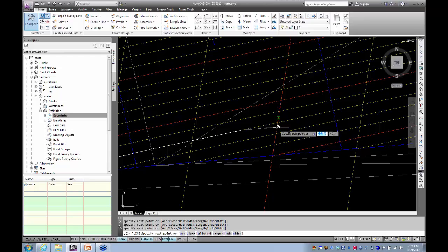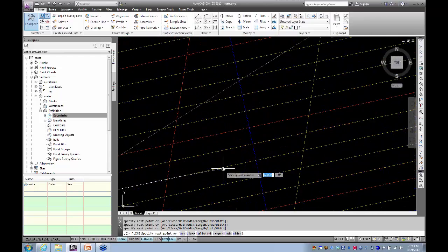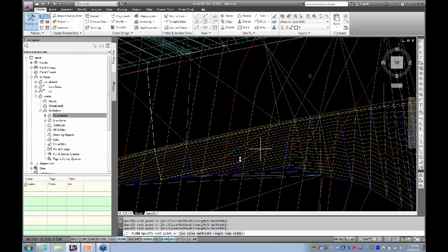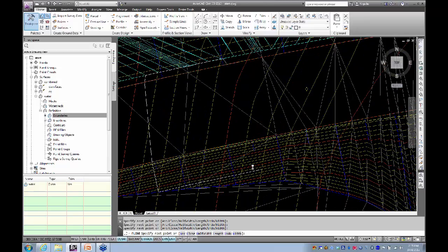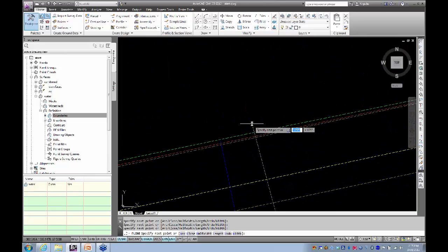So you can make another user-defined contour if you want a specific level you want to run it to. Or we could do this at a rackish angle if we wanted to, but really the bottom of the spillway probably wants to be level, realistically. Let's try that. Back up to the top of the dam.